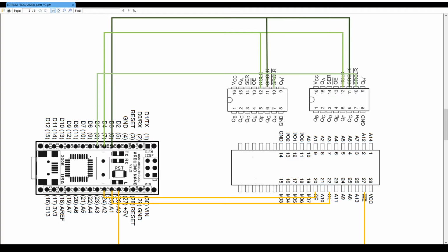And the other clock that we also use, this R clock coming out from pin 4 of the Arduino, is the clock that it uses to latch this result into a second register inside the 74HC595. And the last control we have on these ICs is the clear. I've hooked it up to pin number 5 of the Arduino.